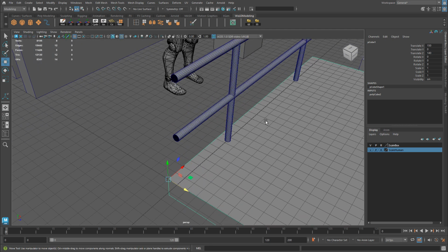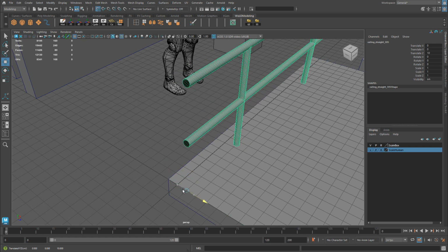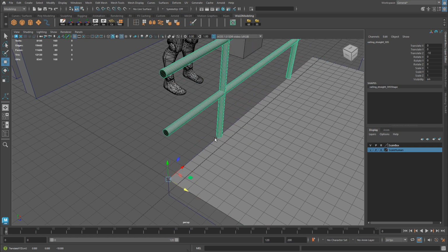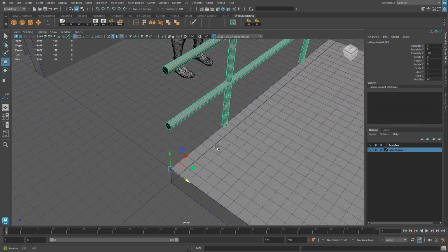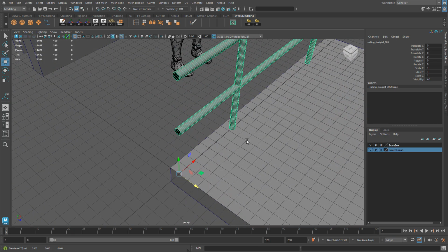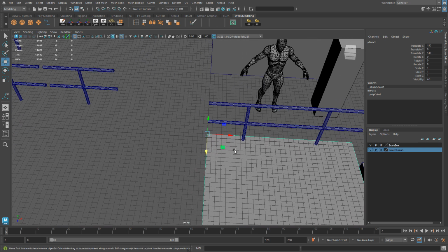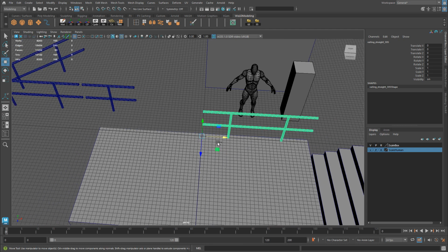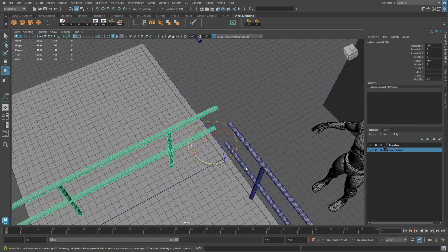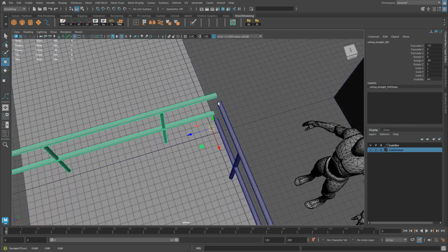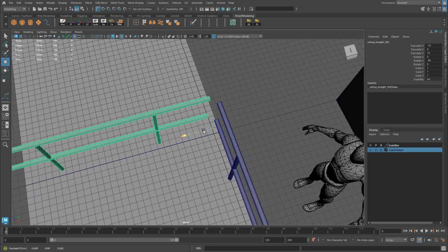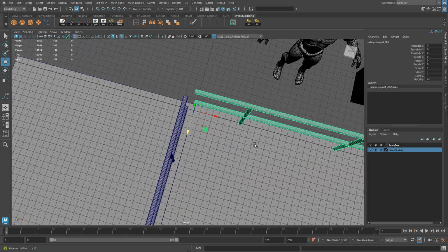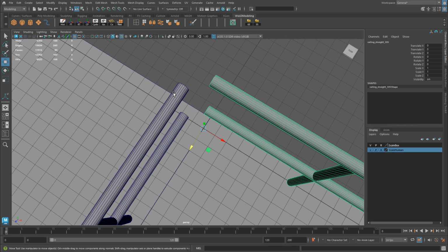This is actually how the railing would be positioned on top of the floor, not overlapping where we have a gap right here where we can see underneath it. It will be positioned right on top of it, like so. So that's what I'm recreating with the floor. I'm going to duplicate the floor and move it over here. Then let's take the 300 and duplicate it again, and I'm going to rotate snap 90 degrees and position it right there. So essentially I am recreating the position of these two railings next to each other, so I can have enough space to bridge between these two to create the 90-degree connector piece.